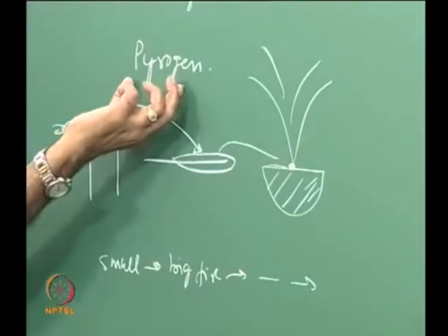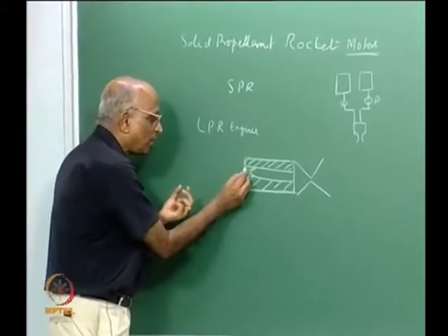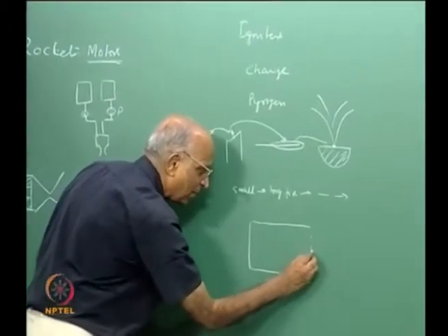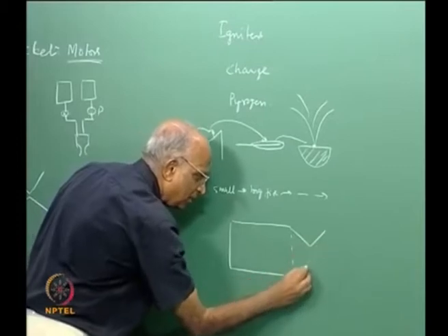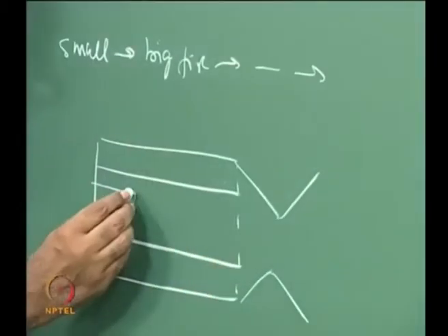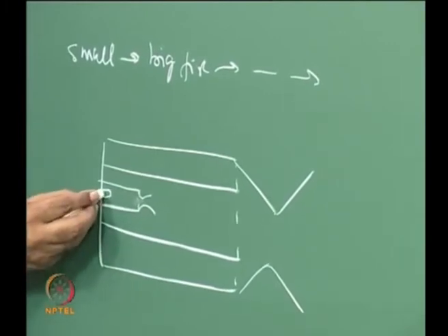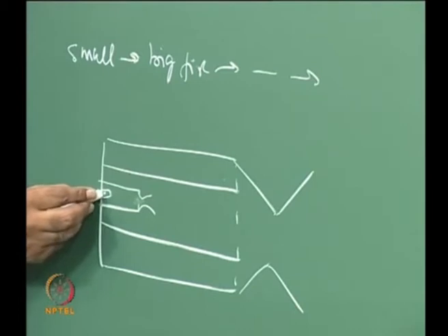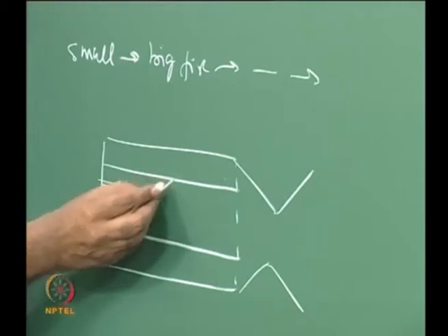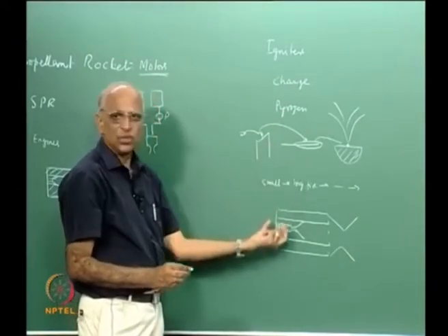And so also in solid propellant rockets, sometimes we use a small rocket motor over here, and that small rocket motor will again, let's put that down, it's something important not only in this subject but in all other subjects. I have a nozzle here, let's say this is my case, I put a small rocket over here, that means I will have something like a nozzle over here, and another igniter for it. This will contain a squib and another one which it ignites, and therefore a small fire makes a bigger fire, maybe a still bigger fire which ignites your pyrogen, and therefore a pyrogen is a small rocket which ignites your main rocket.